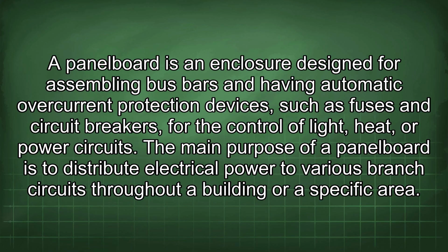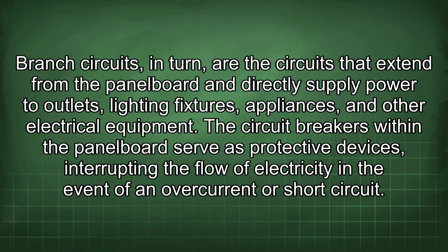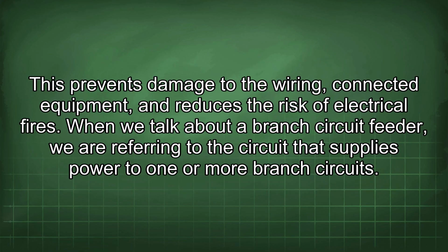The main purpose of a panel board is to distribute electrical power to various branch circuits throughout a building or a specific area. Branch circuits, in turn, are the circuits that extend from the panel board and directly supply power to outlets, lighting fixtures, appliances, and other electrical equipment. The circuit breakers within the panel board serve as protective devices, interrupting the flow of electricity in the event of an overcurrent or short circuit. This prevents damage to the wiring, connected equipment, and reduces the risk of electrical fires.